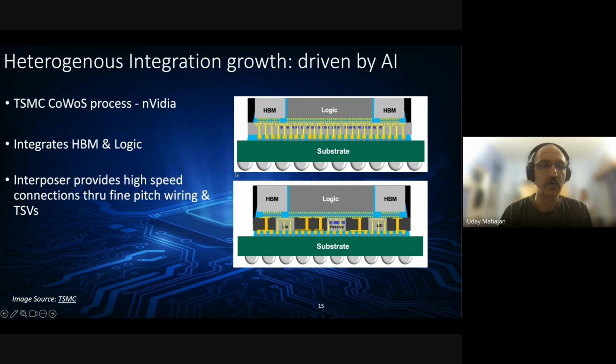It's a little bit, from my perspective at least, like what Intel is doing with its EMIB technology, although I'm not well versed enough to make more than just an informed guess on that front. So this here is a silicon interposer. This here is a polymer, which is why you see separate silicon integrated in it. And these vias are not through silicon via, but they're still through vias.